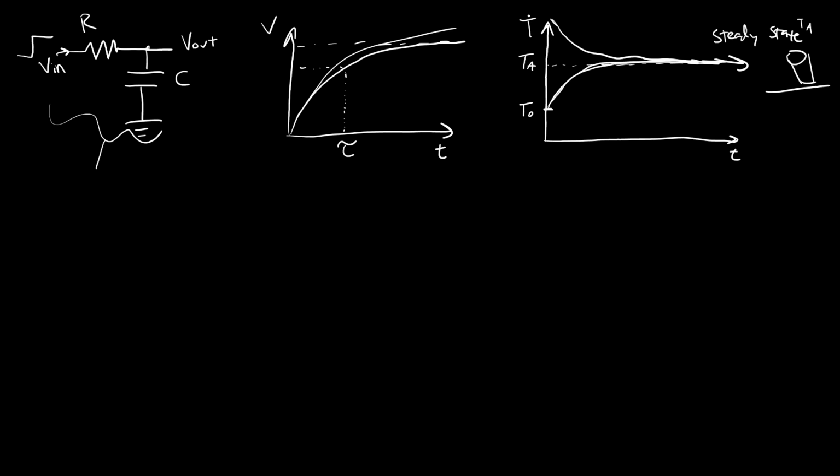And you could pick some other physical variable here, say velocity for terminal velocity of a falling object, and the underlying math might not be exactly the same in all of these cases, but the basic principle is that this is what we mean by a step response. There is just one instantaneous change at the beginning, whether it is the application of a force or a change in temperature, or in the electrical case, the sudden change in an input voltage, but that's it. You only have one change in your input, and then nothing changes forever until you eventually reach a steady state, as opposed to something like driving the input with a sinusoid, which is going to be a different topic in a future video.